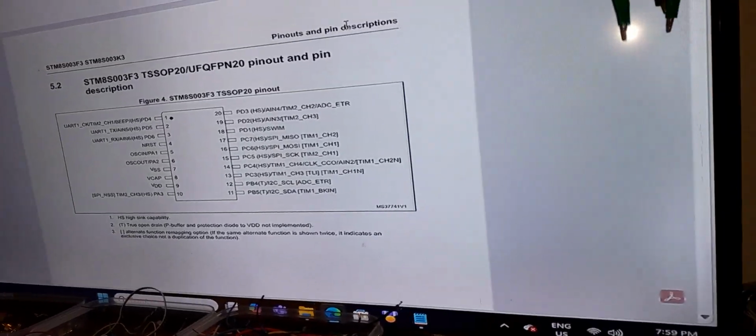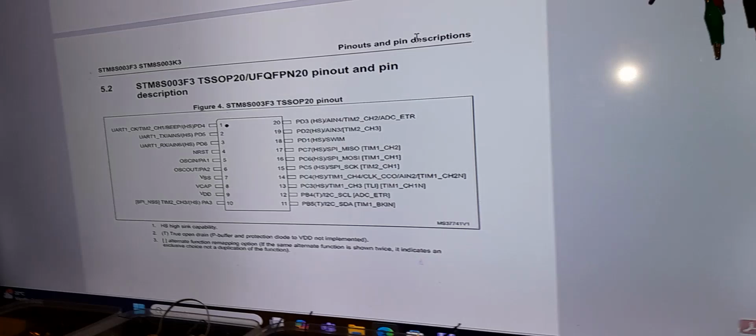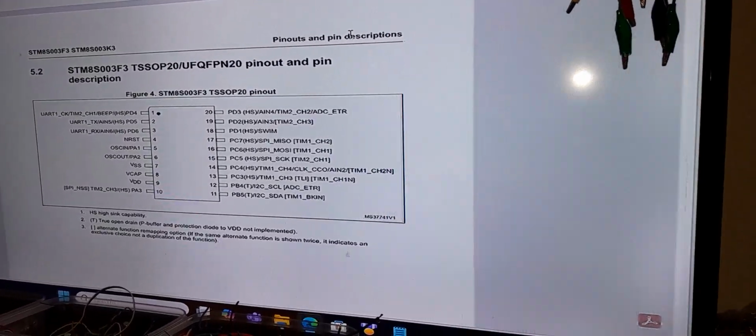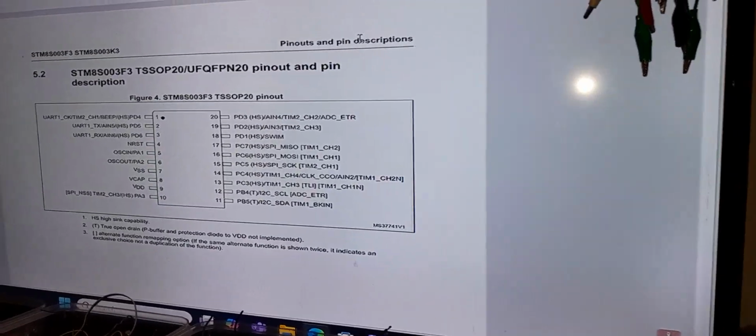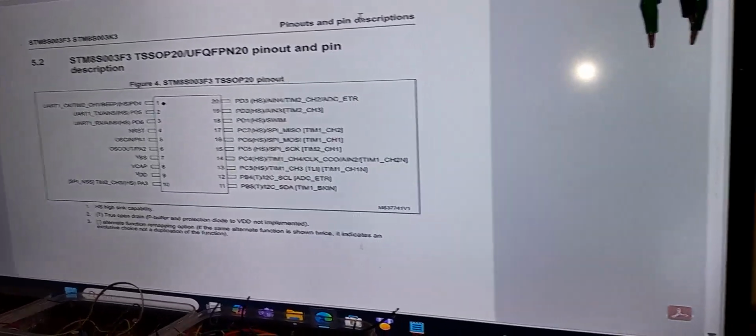That's where I'm going to start, and then we'll move our way back to the regulator's capacitors on its input and output, and possibly the resistor value too. And like I said in the last video, I'm not too sure that the ground plane on this board is done properly too, so we'll have to look at that too. So I'll just pause the video whilst I find the part in the data sheet where you calculate the value for VCAP, and then I'll come back.